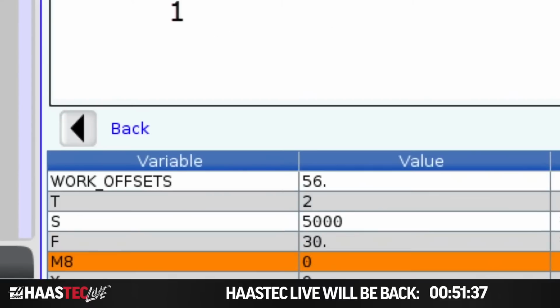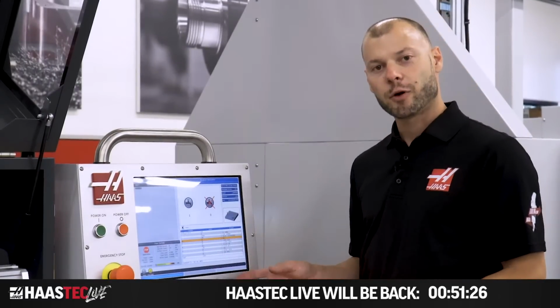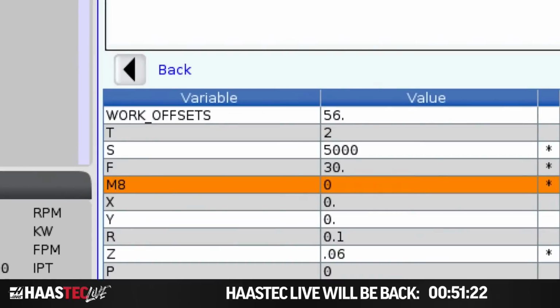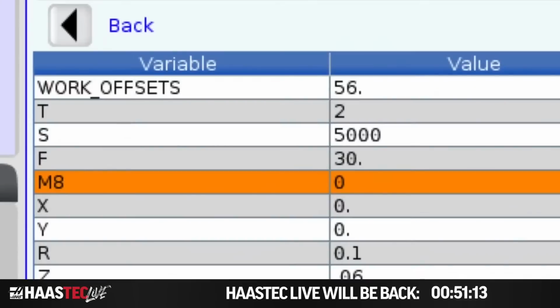Next, M8 is asking coolant or no coolant. This is a code all new machinists will learn very early on, and this is one way that VPS reinforces codes where applicable. So if you're choosing a canned cycle or coolant on, coolant off, we're going to reinforce that with the actual M or G code in the template. In this case, we don't have coolant, so I'm going to enter 0.